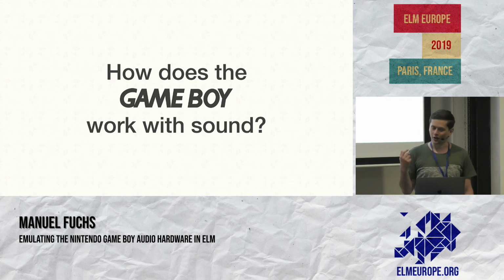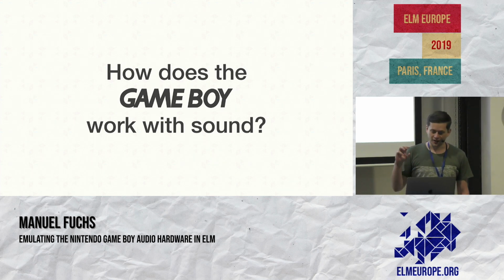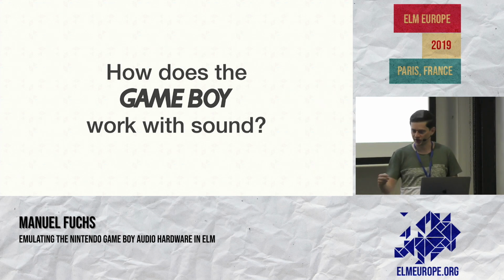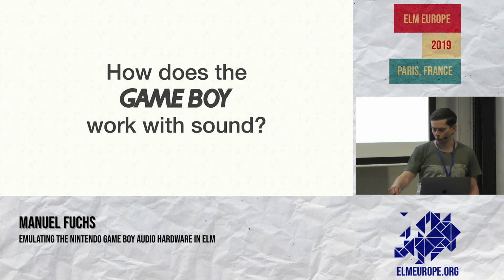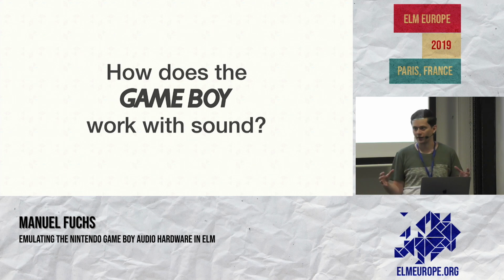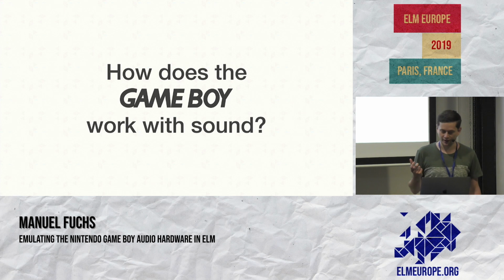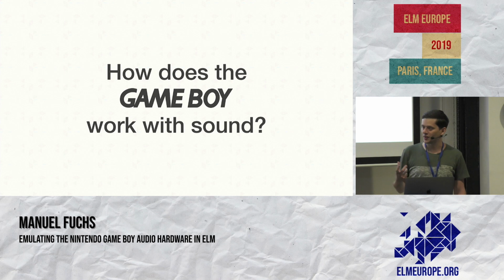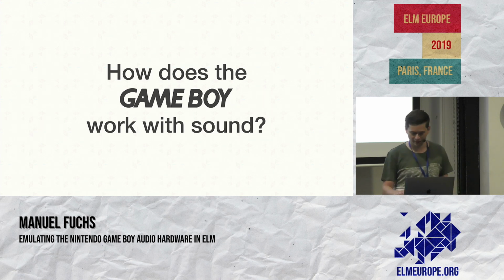So the solution here is on-the-fly audio synthesis. Games send control information to a specialized chip that produces the sound based on given control parameters. This is similar to playing a keyboard. I select a voice on my keyboard and press a key, and out comes something like a flute that plays an A. And I only need to remember what key I pressed and what voice I selected to reproduce the sound later. I don't need to actually record it. This comes at the cost of a limited set of voices and limited polyphony. And this is also the reason why so many Game Boy games sound so similar to each other.